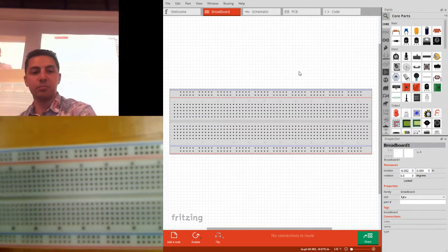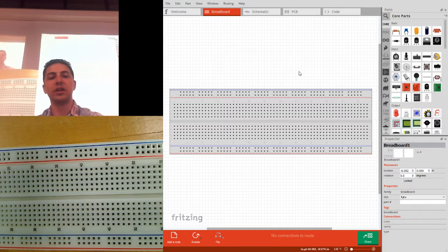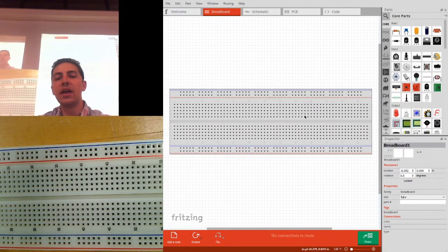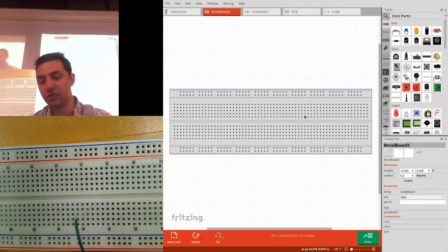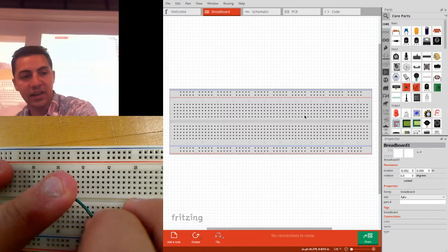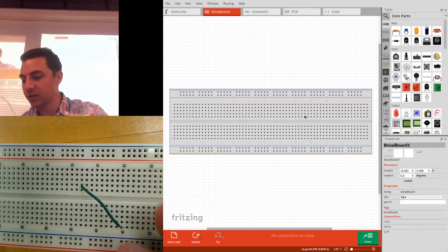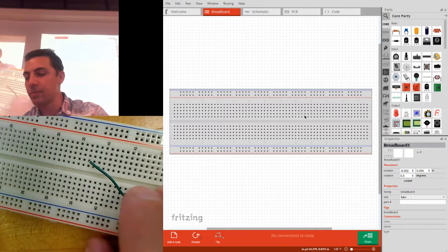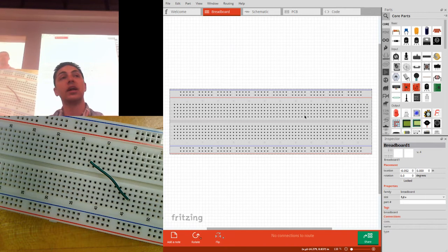You'll notice it looks pretty much the same as what's on my screen in fritzing. The nice thing about a breadboard is you can take hookup wire, 22 gauge wire, and you can connect it up just by sticking it into one of those holes, and then you stick it somewhere else, and that makes a firm electrical connection, firm-ish. Okay, there are limits to what it can do.